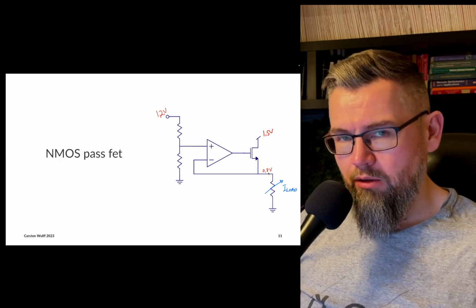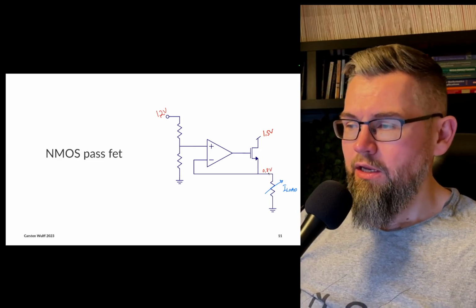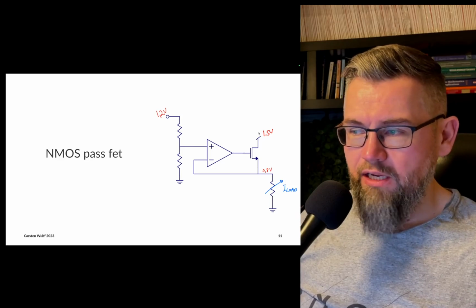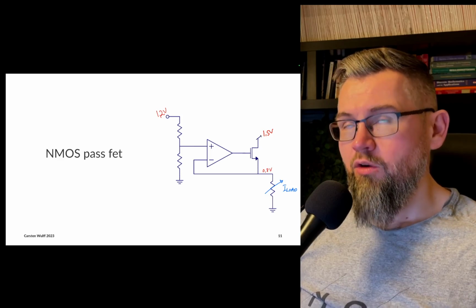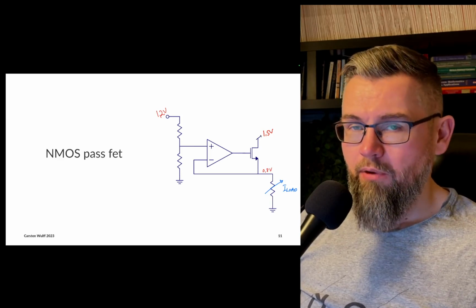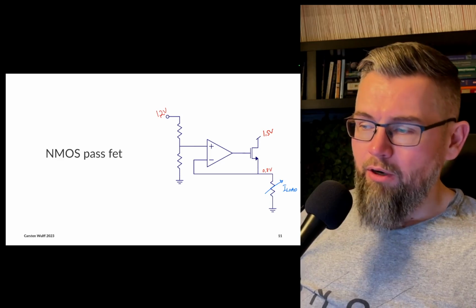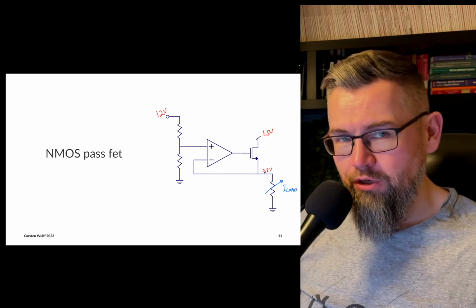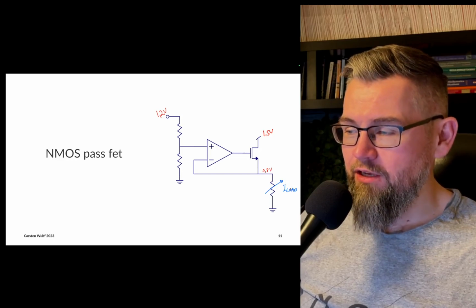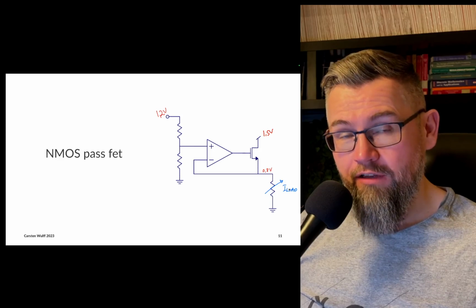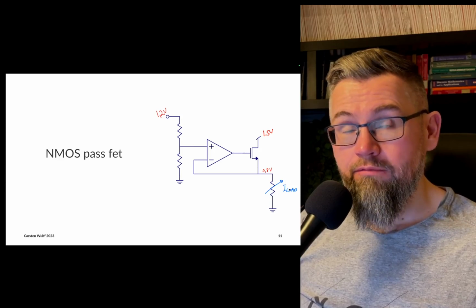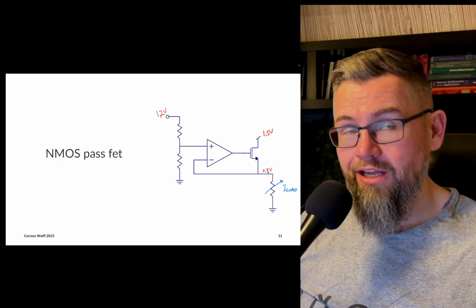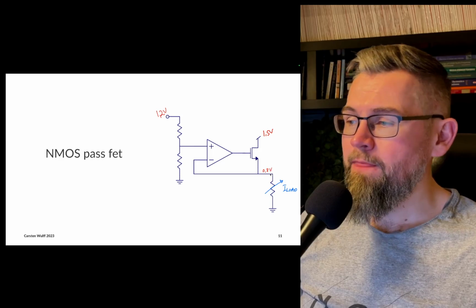One fundamental problem with linear regulators is that whatever load I have here, I'm pulling the same current from the 1.5 volt, which means if you look at my power consumption, well, let's for the moment say that the 0.8 volt was 1 volt, and we have 10 milliamps, then we have 10 milliwatts consumed in the load, or 8 milliwatts for 0.8 volts.